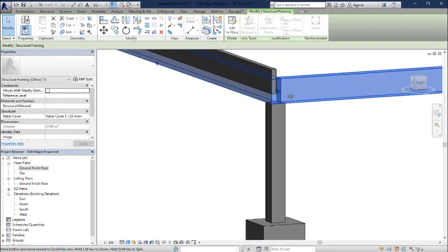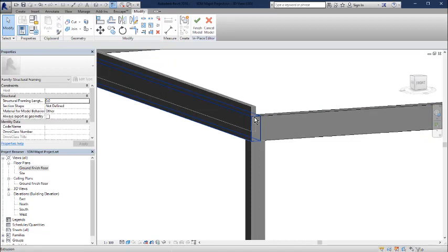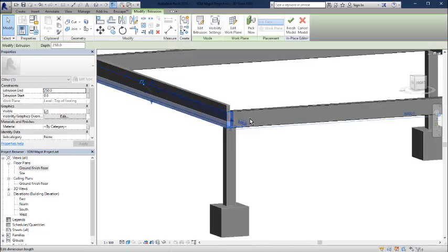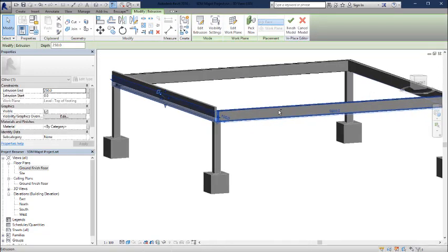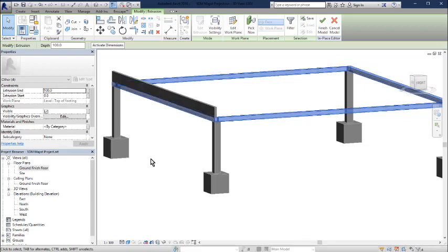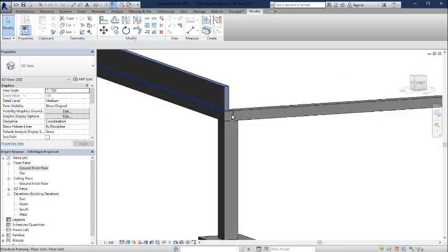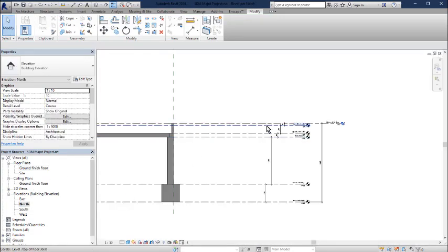We're going to go back into our bearer joist here. We're going to double click that to go into that, and we are going to edit these. So we're going to select all of them holding Control, and we're going to set the extrusions end to, I believe it was 100, right? So it's 100 by 100, apply, there we go. If we look on our north view, we are in alignment with everything.